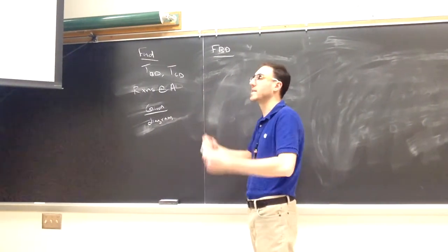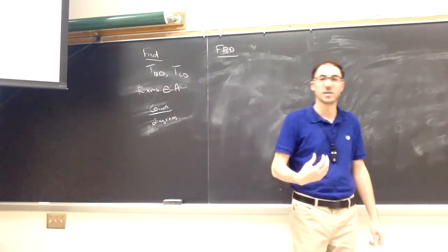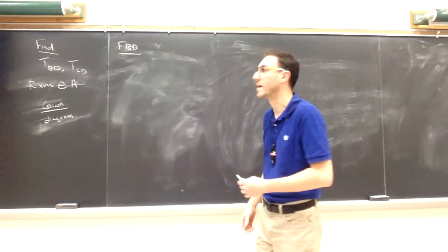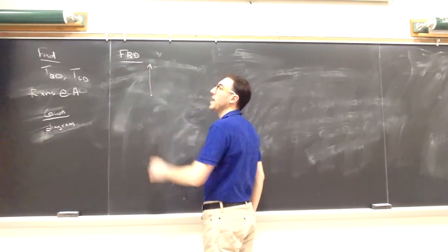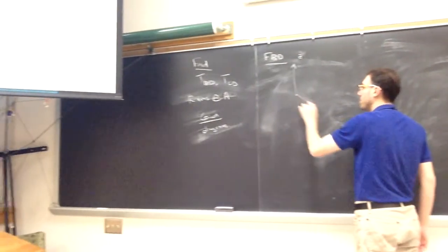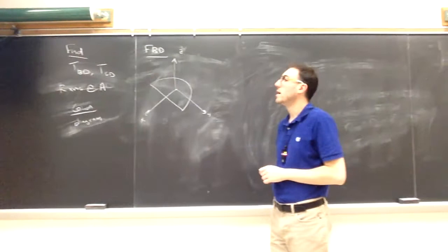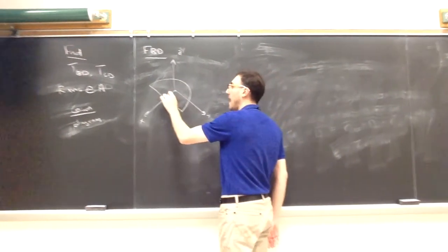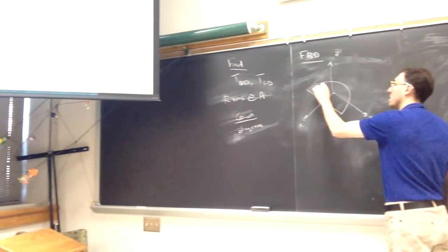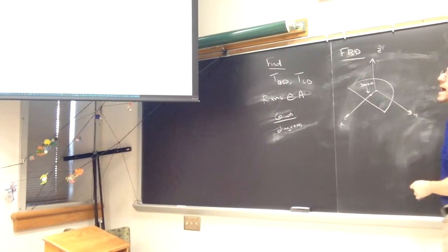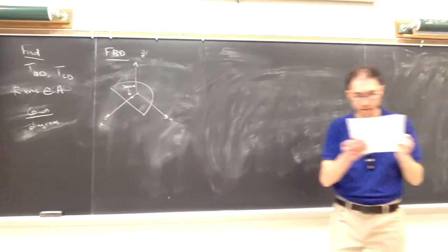We're going to disconnect it from the ropes it's attached to at B and C, which means that we'll be able to see the tensions in those ropes as they're going to be affecting that blue platform that we kept. Keeping their given coordinate system. Okay, so there is the platform. We have one applied force acting on it, that 300 Newton force. Acting at, they actually don't give that a name. In my notes, I just called it E.